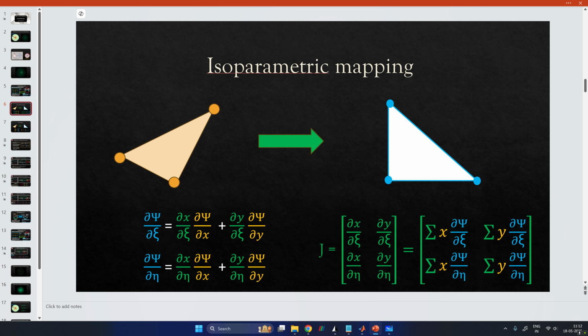So psi is your shape function inside this triangle, and we are interested in the partial derivatives of the 2D psi shape function, in the xi and the eta direction. Since the polynomial is curved in both directions, as we have already seen on those surface plots, you have to apply the chain rule in both directions.